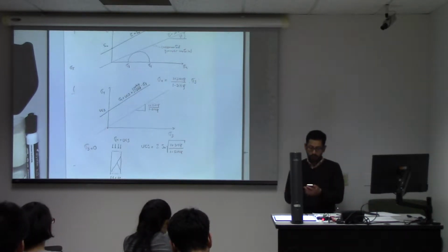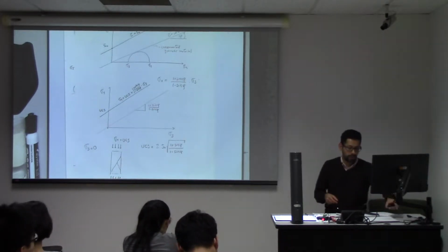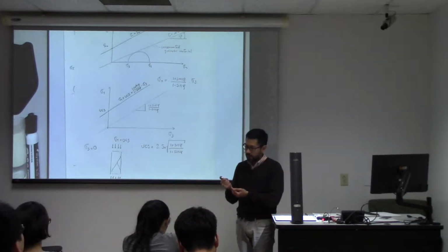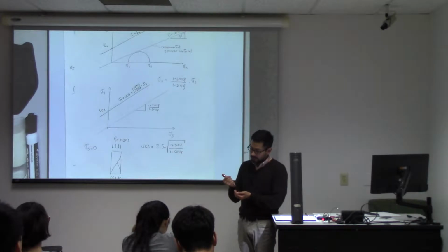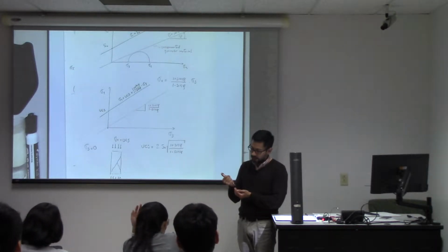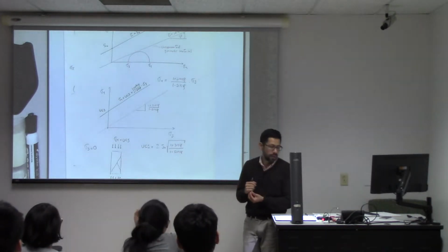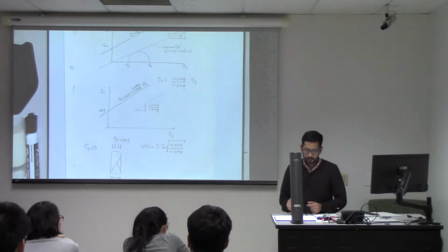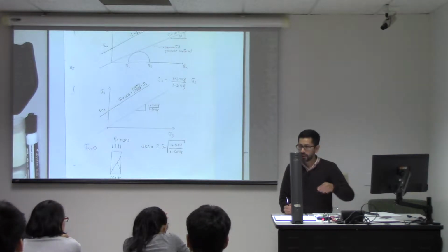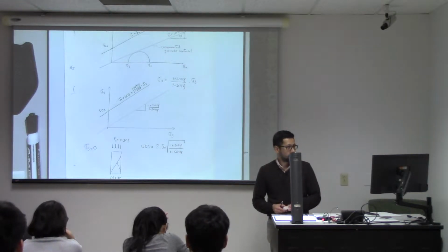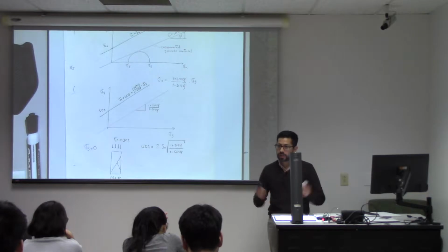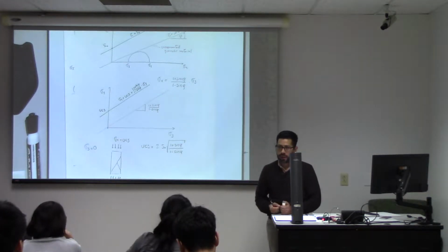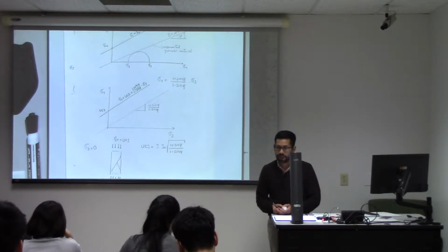All right, so you may wonder now how we measure this stress sensitive part. And the stress sensitive part is going to be measured with what are called triaxial tests. A triaxial test is a test in which you subject a porous material to stresses in different directions until you get failure. And that will be a triaxial failure test.